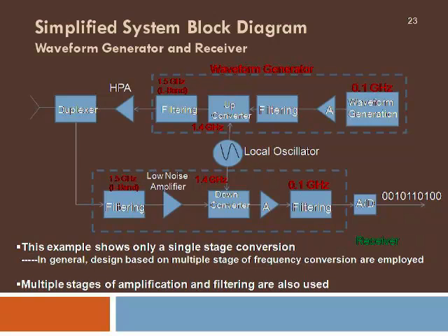Using the same local oscillator as earlier, we are now going for a down conversion by selecting the output filter for the difference signal. So the 1.4 GHz local oscillator signal is mixed with the received 1.5 GHz signal, and the difference between them is going to be the output from this. So your 100 MHz signal is now amplified by a normal amplifier.